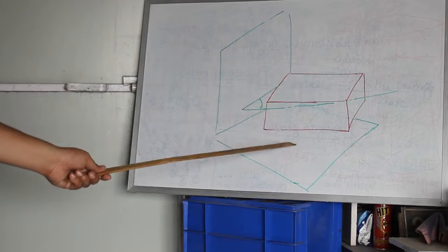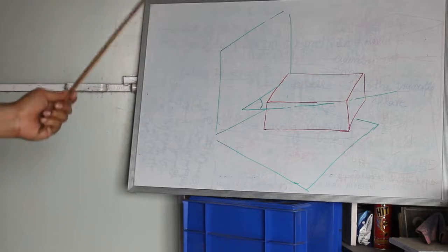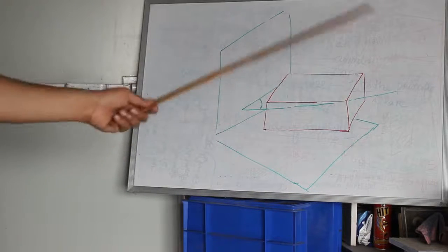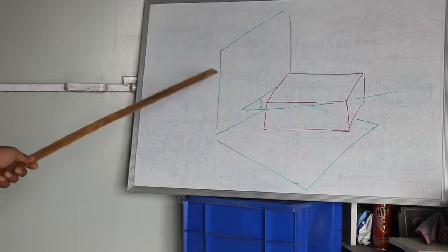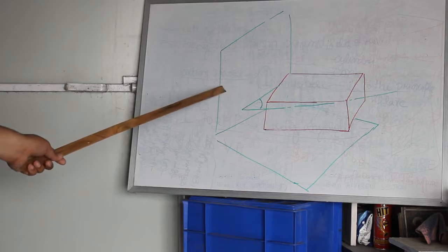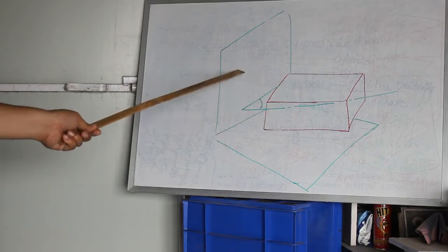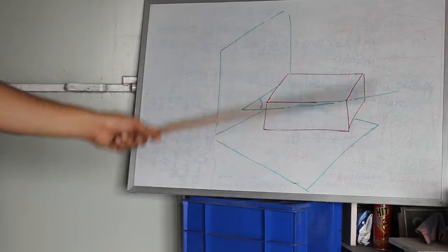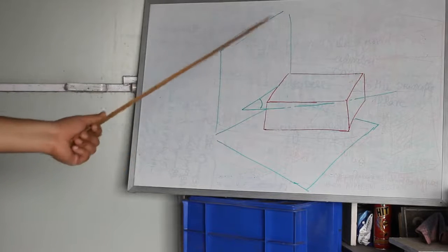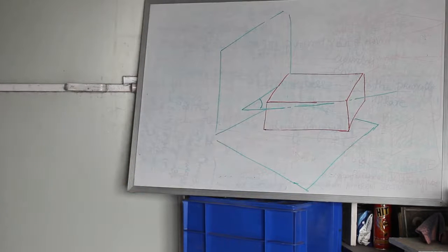Then the face of the solid is also parallel to HP, and like we initially solved the question in phase 1 and phase 2, it will also be solved in phase 1 and phase 2, with the assumption that in phase 1 the axis of the solid will be taken perpendicular to the vertical plane, parallel to HP, and in phase 2 the actual angle of inclination with the vertical plane will be taken, and then it will be projected as per the statement in the front and top. So phase 1 and phase 2, like this.